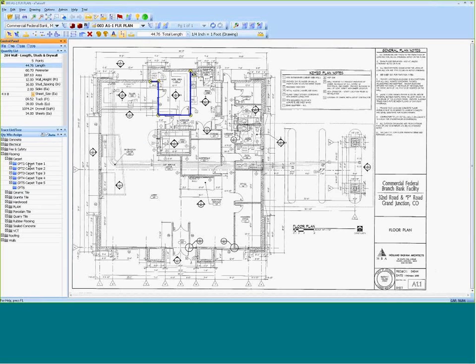I'm going to go ahead and measure carpet, okay? And I'm going to double-click here, and I measure, and enter this same room that we did a minute ago. I have extension data here because what I'm going to do is I'm going to take the perimeter and subtract how many doors there are. So there's one door, and use rubber base in that room. So what it did was it took the perimeter and subtracted that door 3 feet and gave me that.